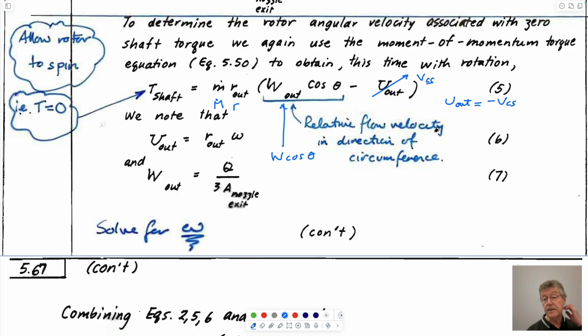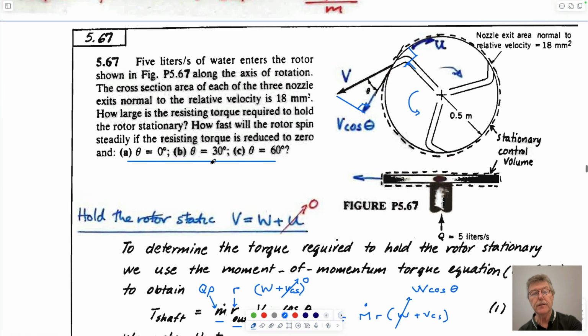Just a sign convention. And so I won't belabor the point, but the ultimate goal then is to be able to now take this expression, and you can do two things with it. You can calculate what the maximum shaft torque would be for flows coming out not just at 0 angle, when this would be maximum, but also for these other angles here, just by substituting it.